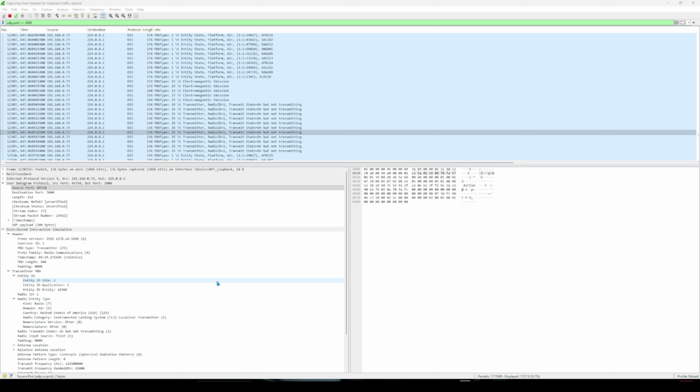Then the entity location is ECEF meters, big endian per the spec. The entity orientation gives the yaw, pitch, and roll in radians. And the entity marking field carries the call sign as ASCII: DLH105, BAW472, and whatever's flying at the instant. Any DIS federate on the network can read this and add the aircraft to its own scope.